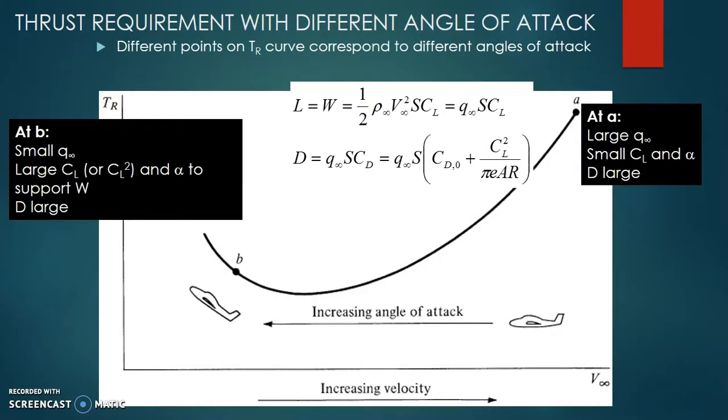Now, let us look at a different angle, which means angle of attack. And where is it coming? It is coming in the maneuvers that we have to do. You remember this equation, right? At increased velocity, the thrust profile goes up and down like this. At one point you have a very high angle of attack and very low velocity to sustain that lift, which means in these high angle of attack operations, the thrust requirement is actually higher than the optimum low.